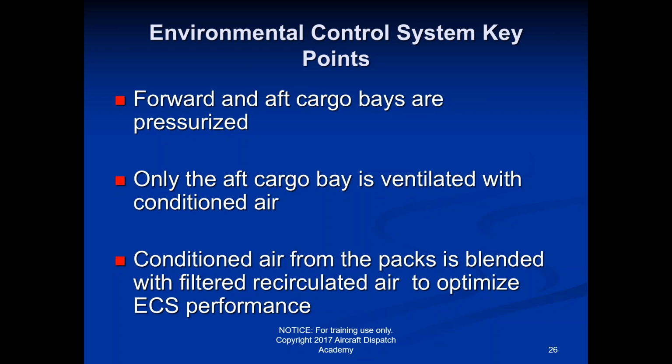A lot of times, if you have one of these cargo fan MELs, the restriction on the aircraft will be that it says no animals. As a system controller, you are supposed to relay the no animal MELs downline to the stations. Now, some of these stations can look up MELs, and even if somebody doesn't call, they can still have ways of seeing that it's a no animals aircraft. But you do get into situations where somebody didn't call and then somebody put an animal on one of these airplanes, and depending on the length of the flight and the altitude that it goes to, said animal may or may not live.